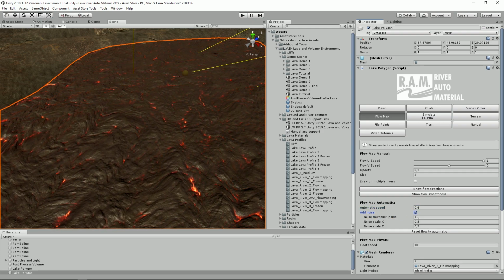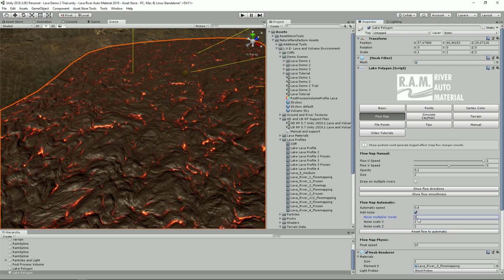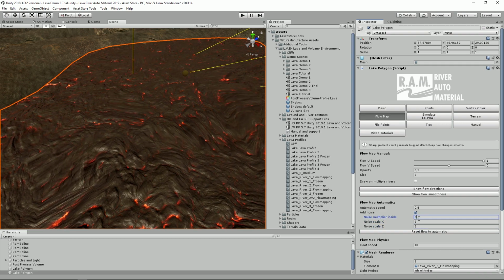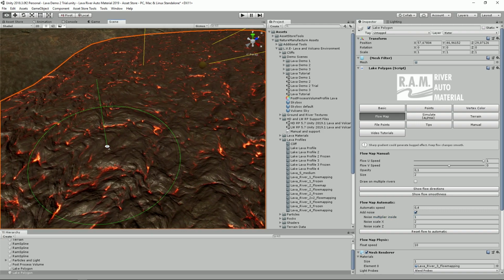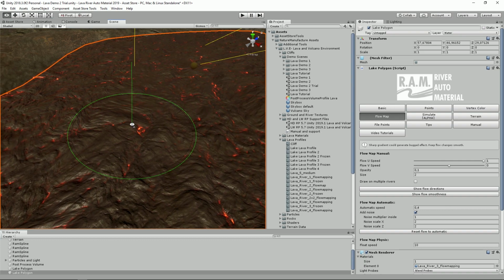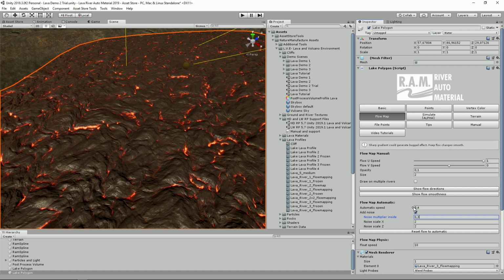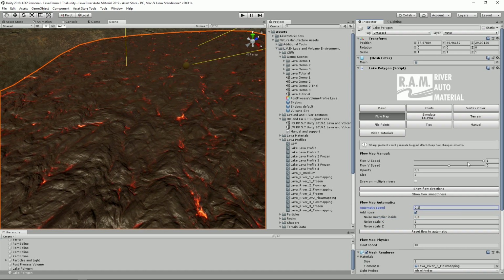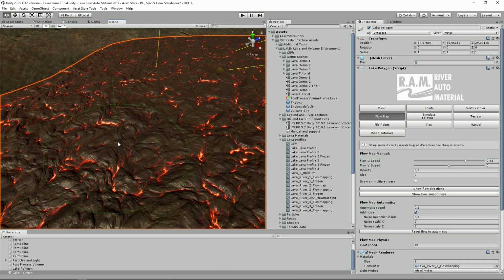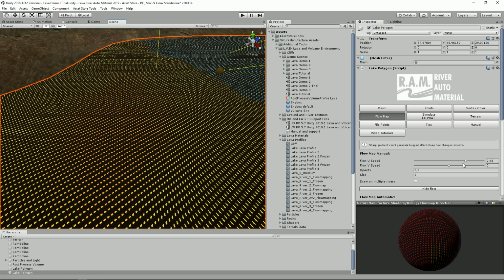Of course, please, like I said before, keep it very soft, because we could get errors in the UV if the speed increases too fast over a very short distance. Because yeah, it's a tessellated shader. Even on a non-tessellated shader, which is much more flexible, you could get a pretty bad result if this is too sharp. Of course, you also have a manual painting tool, so you could paint the Flowmap manually on your lake as well.